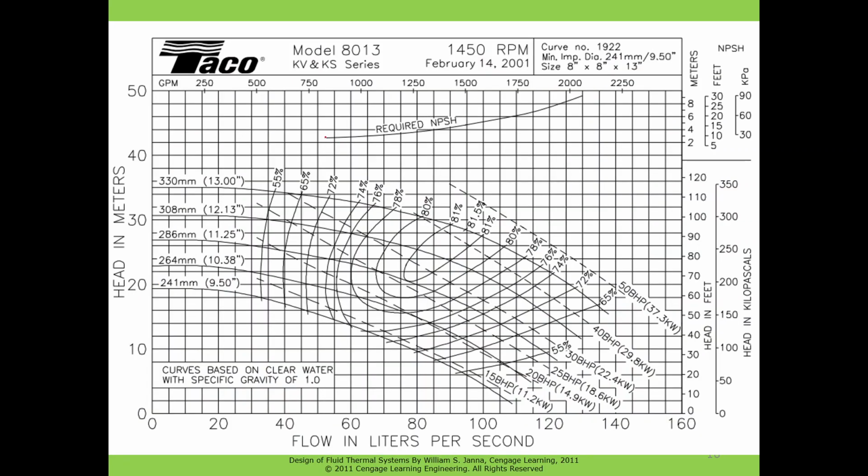This curve indicates the net positive suction head required. Corresponding to any flow rate, like 80 liters per second in the pump, it touches the curve here, and then you take this line to the right hand axis and touch it here. Let's say some 3.9 or 3.8 is the net positive suction head required by the pump.